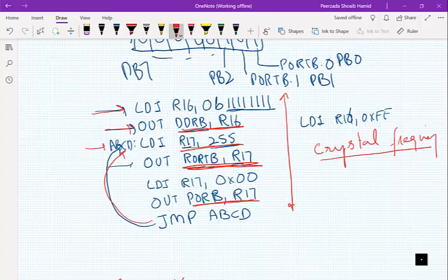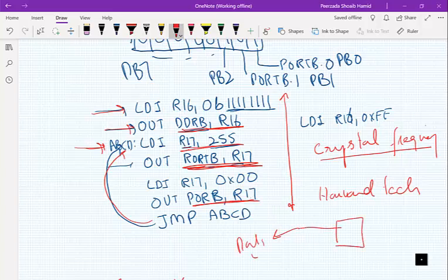And the second thing on which the rate of execution of instructions depends is the internal architecture of the microcontroller. What's the exact IC technology, or the exact technology of the processor we have used? For example, in the Harvard architecture, we have separate data memory and code memory. Since code is stored separately from data, we have separate buses.